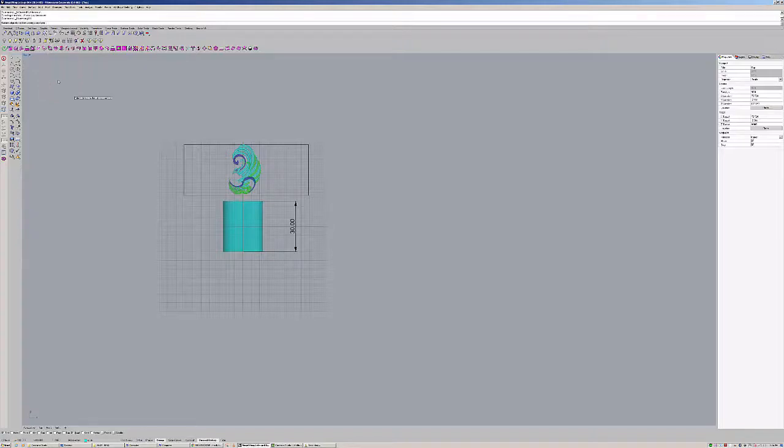So we left click on flow along surface. Now it's asking me to select the objects. So here it is, all inside the box. I'm selecting the objects, and right click when you're done. Now this is very important. Up here there is the word plane. We click on the word plane, and start with the first corner, left click, and drag down to the second corner, left click.